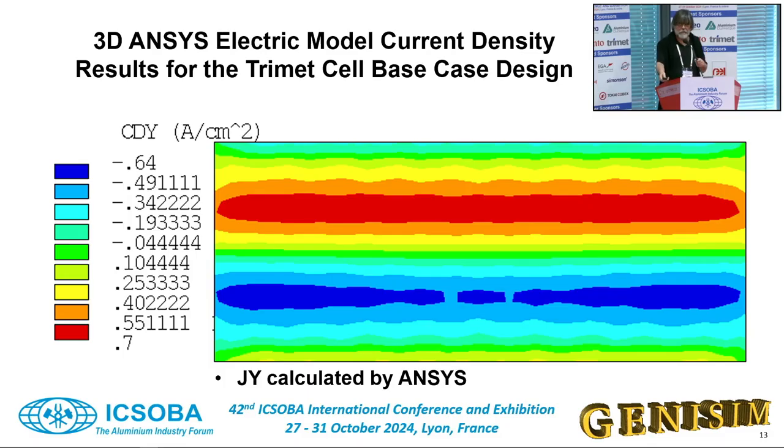And because the metal is so conductive, every discrepancy with two models or two geometries, everything will be picked up by the horizontal current. If you have more contact resistance, slightly different size of bar, slightly different ledge, different current coming from the anode, everything will go. Adjustment is done in the metal pad. So that means that this solution is very difficult. That's the way it is. The metal pad is doing the adaptation. So the current density there depends on everything you're doing.